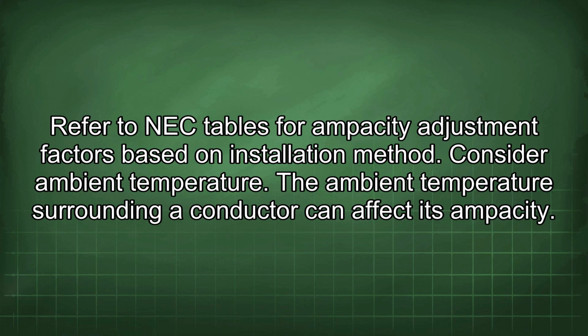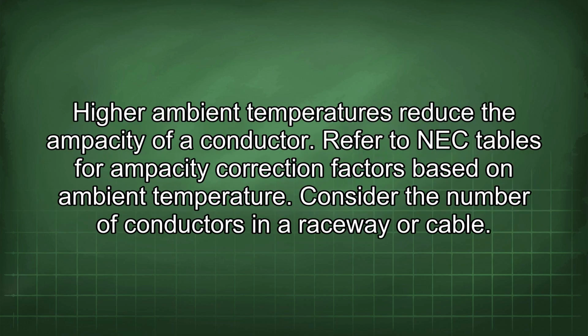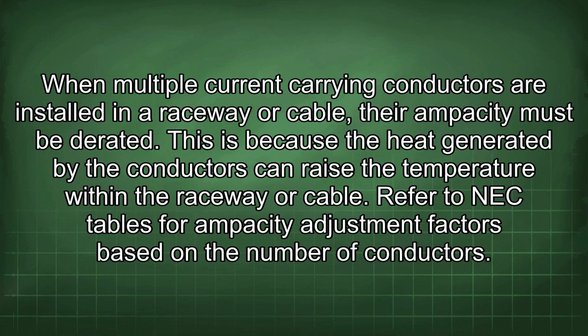Consider ambient temperature. The ambient temperature surrounding a conductor can affect its ampacity. Higher ambient temperatures reduce the ampacity of a conductor. Refer to NEC tables for ampacity correction factors based on ambient temperature. Consider the number of conductors in a raceway or cable. When multiple current-carrying conductors are installed in a raceway or cable, their ampacity must be derated. This is because the heat generated by the conductors can raise the temperature within the raceway or cable.